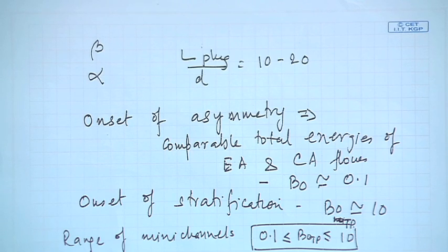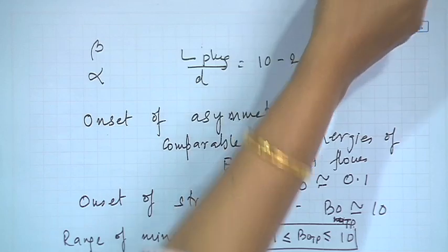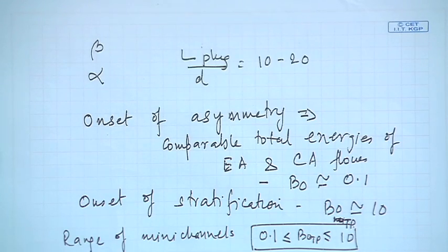It will be interesting to note that if you compare this value with the table that I had shown yesterday, you will find that all the transition values given by past researchers lie within this domain. So, this model could predict a large number of things, and I think we have not tried it, but it should be quite applicable for gas liquid systems, slightly inclined flow patterns, and it can be used for other flow patterns as well.